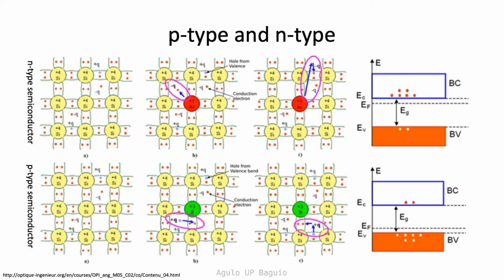This highest energy state where electrons are found is called the Fermi level. In this case, when a group 5 atom substitutes a group 4 atom, these energy states are created, forming this new Fermi level. Only a small amount of thermal energy is required to bring these electrons from the Fermi level to the conduction band. When electric potential is applied, current is obtained through electrons that move around the silicon network of atoms, also called the lattice. This kind of semiconductor is called an N-type semiconductor.